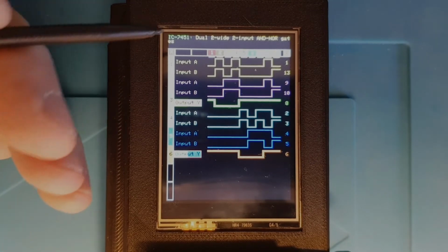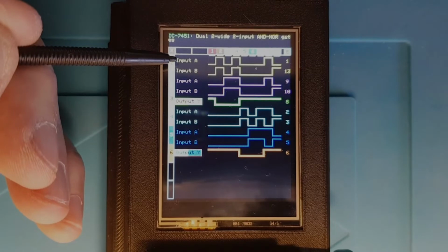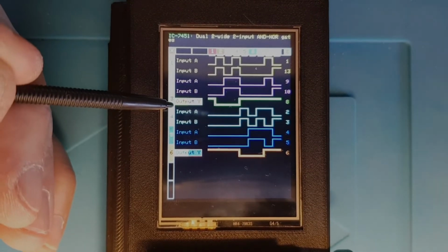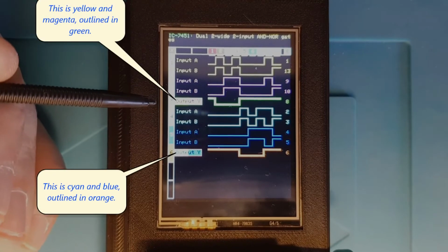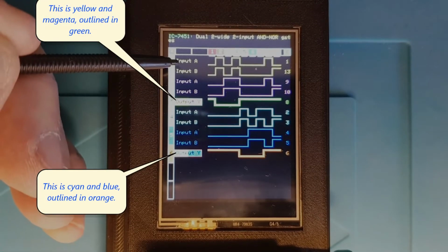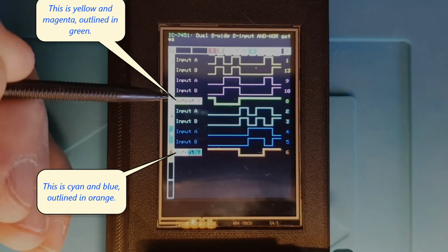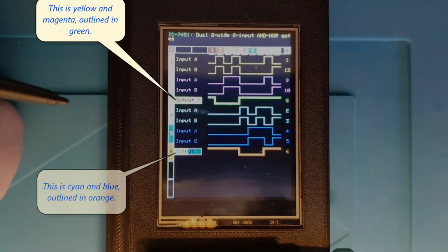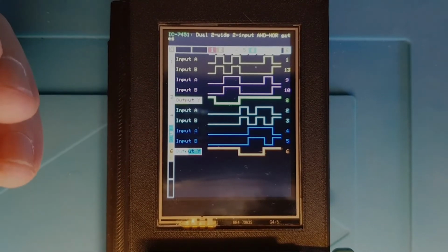Right, so on this one, these are the 2-input AND gates, and the outputs of those feed into this NOR gate. So because the output of element 3 is associated with elements 1 and 2, that's why we've got this double colour bar here. It's outlined in green and the line is green. So again, we've got thin for inputs and thick for outputs. Right.